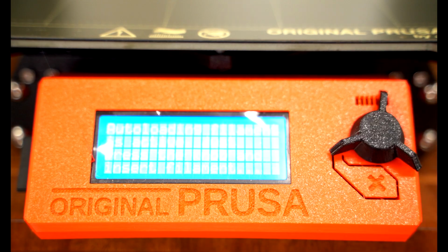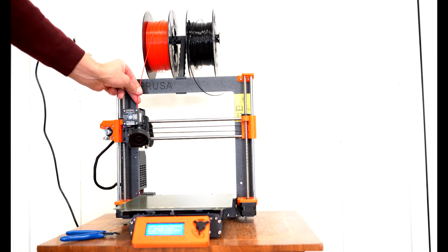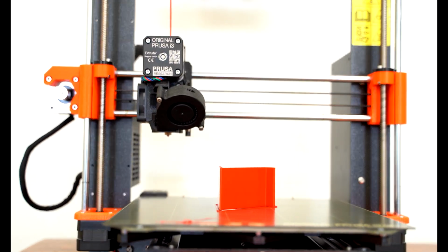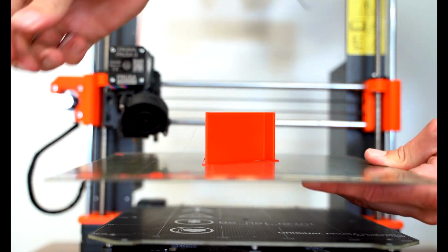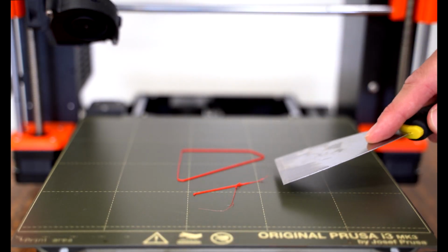Cut your filament with a dedicated tool so you can insert a sharp end when you load your filament. Carefully remove your 3D print with a dedicated tool once it is ready. Make sure that you don't hurt yourself on the hot 3D printer.